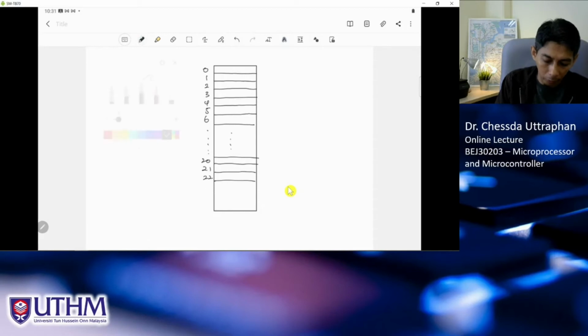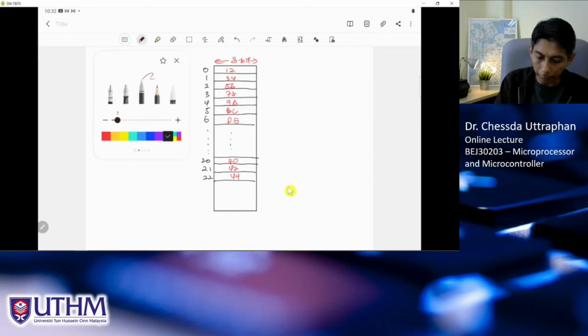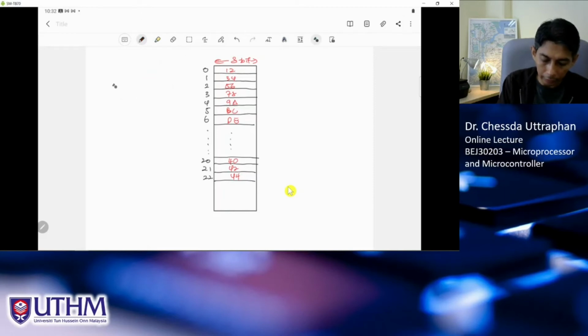And inside here is the program. And again, the program is stored in the form of binary number. And let's say, again, this is 8-bit. So the program is just a data, for example, 8-bit data like this. So again, in our microprocessor, we have what we call a PC, right? Just now to point to the next instruction to be executed.